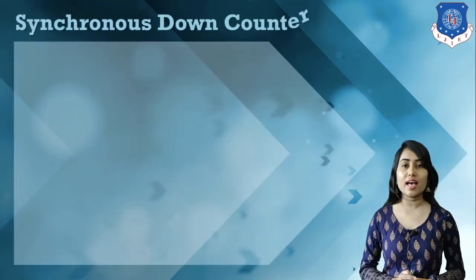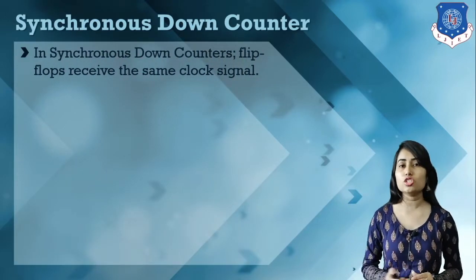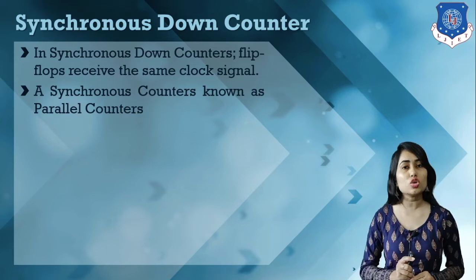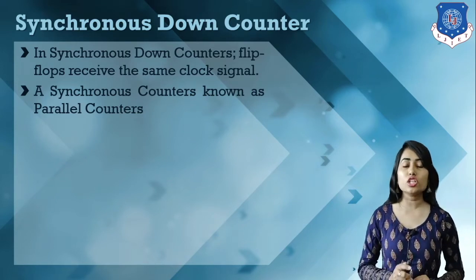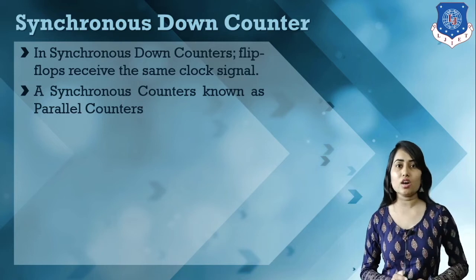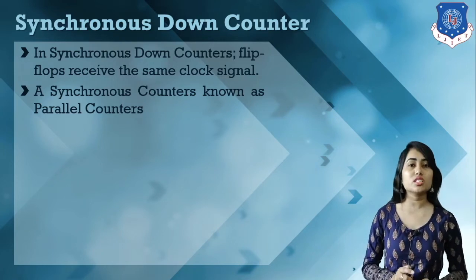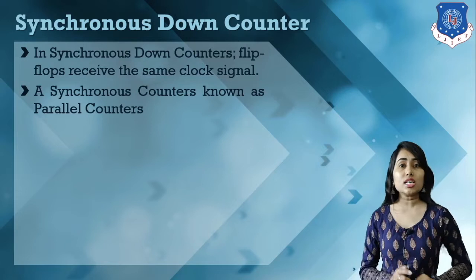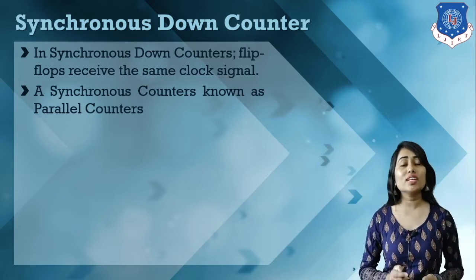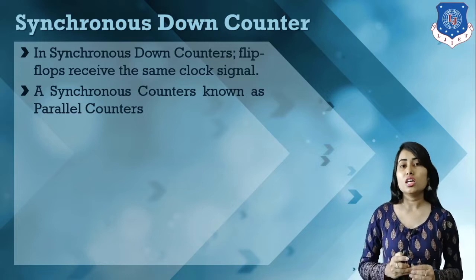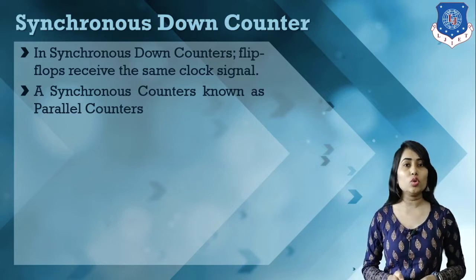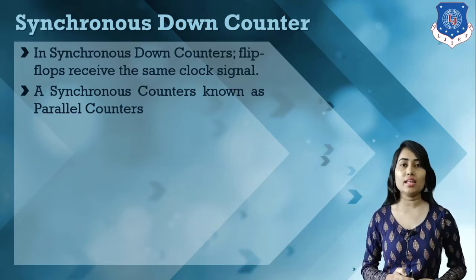As this synchronous counter has the same clock signal, it is also known as a parallel counter. It is known as a parallel counter because all flip-flops receive the same clock signal, such that all flip-flops will work simultaneously, in parallel.